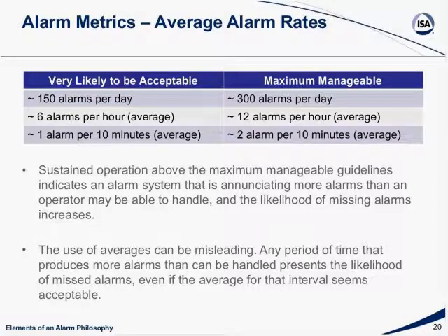And this is out of ISA 18.2, and EEMUA has the same standard, so you really need to take a close look at this. This is kind of standard throughout the industry. When you're developing your alarm philosophy, just kind of copy and paste this in, because this is what everybody has.